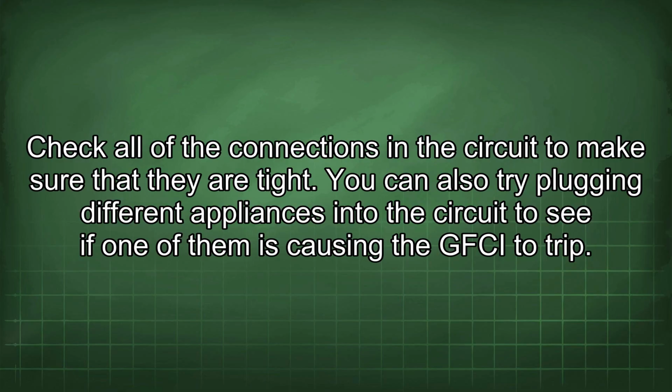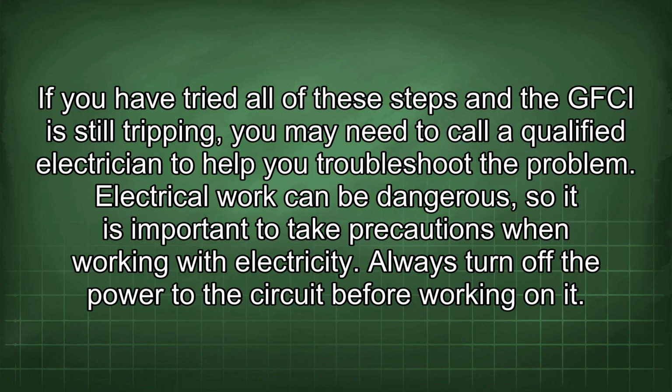You can also try plugging different appliances into the circuit to see if one of them is causing the GFCI to trip. If you have tried all of these steps and the GFCI is still tripping, you may need to call a qualified electrician to help you troubleshoot the problem.